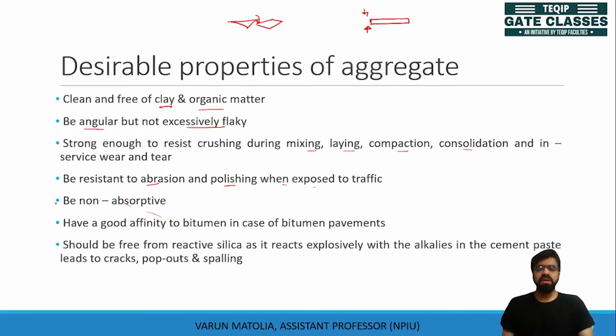The aggregate should be non-absorptive, meaning there should not be any tendency of absorption of water, because if they absorb water during low temperature durations, the water will freeze, the volume will increase, and this will cause disintegration of the rocks or the aggregates.